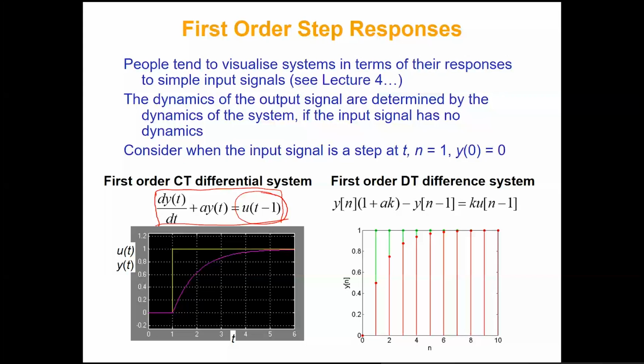in MATLAB using Simulink. In Simulink, we can just drop a box, and inside the box you can write a differential equation, dy by dt plus a times y of t is equal to x of t. And for the x of t that is coming in, you can just give different values. Now x of t can be a step signal u of t, it can be a delayed step like you see here, u of t minus 1.